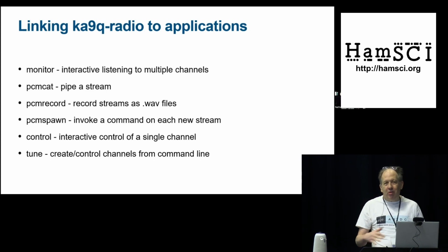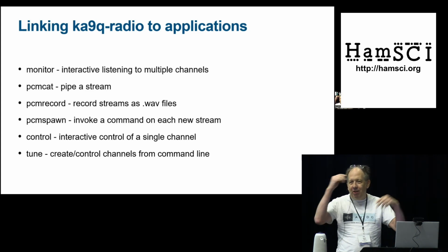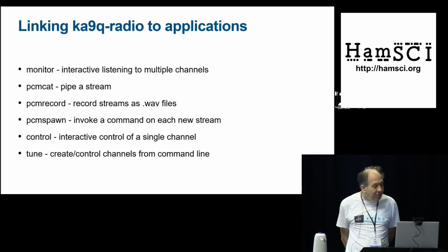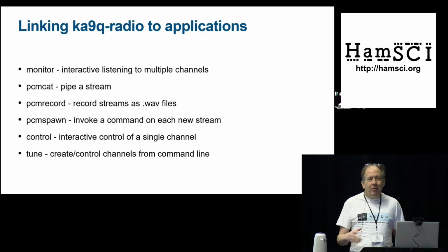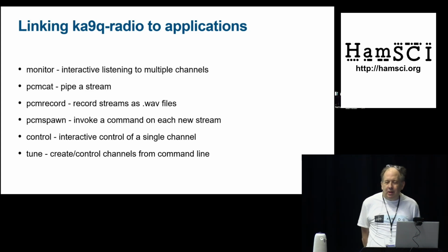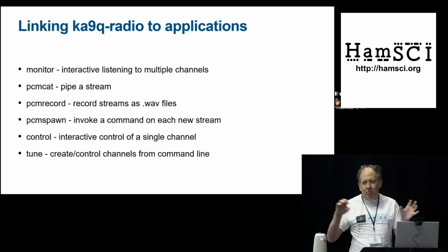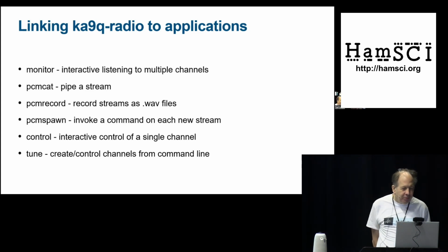You turn this on and somebody talks. It's like listening, you're in a stadium, because the delays to all the repeaters are slightly different. So to help that, I put in a feature where if you listen in stereo, it will place each channel at a different place in the stereo spectrum so you can keep them apart. Turns out, I don't think that's original. I think some airplane cockpit audio panels already do this, because you often have multiple radios you have to listen to when you're flying a plane, and it's helpful to have the virtual speaker be in different locations. So that works pretty well. It also automatically notches out PL tones, because I don't do that in the receiver.